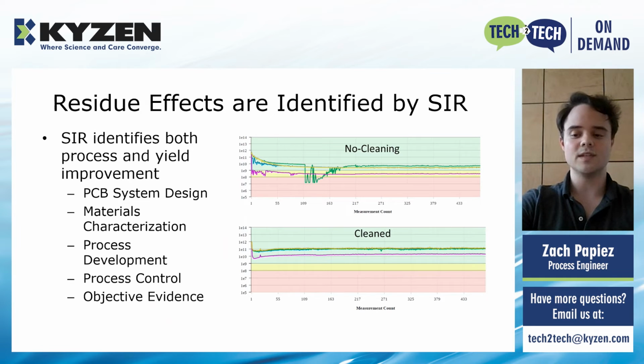Finally, even mild residue effect can be seen through SIR when your boards haven't been cleaned or cleaned well enough. Some of these effects might not be technically classified as a failure by IPC standards, but setting up a cleaning process that foregoes the residue effects altogether may be desirable.